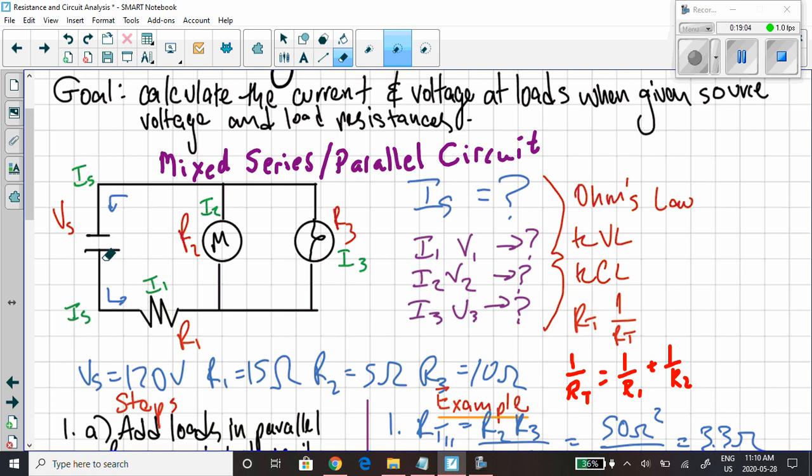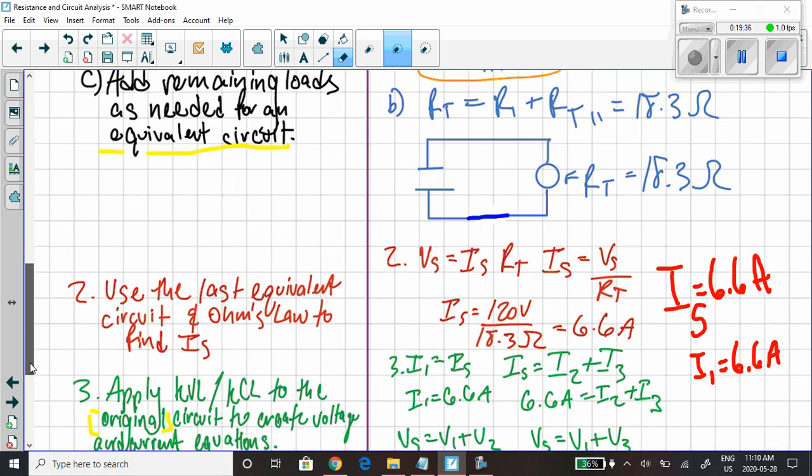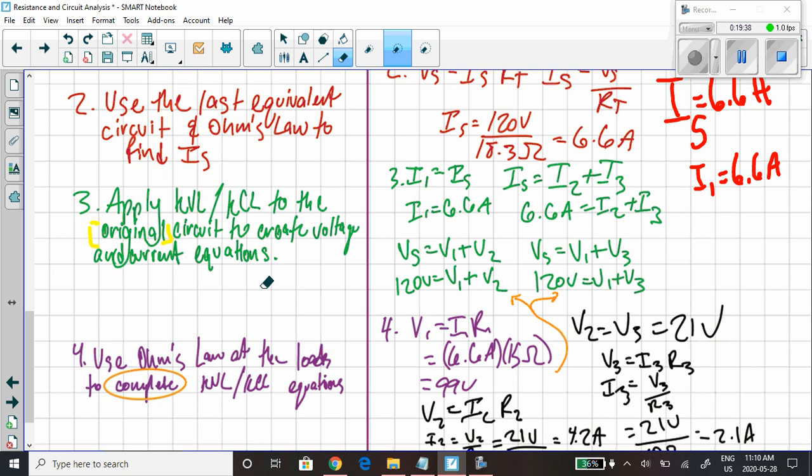So we got the voltage source here. Then we got the first load. At the first load, we have R1, I1, and you would have a voltage drop V1. Let's keep on following the path of the current. We run it here. This is the motor. The motor has a certain current through it, I2, a certain resistance, R2, and a certain voltage drop, V2. And then the current goes back home. So that is our first Kirchhoff's voltage law equation. Look, Vs is equal to V1 plus V2.